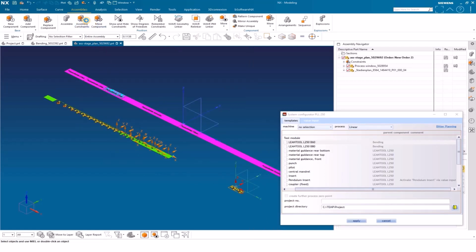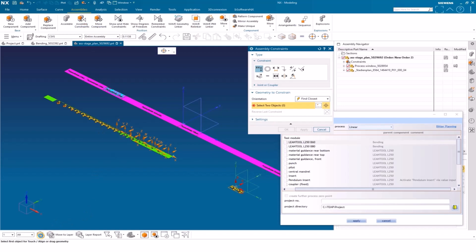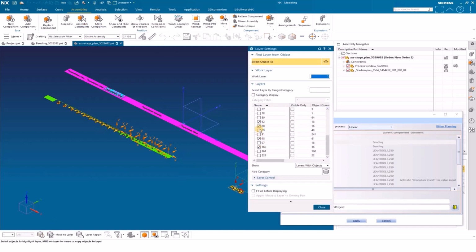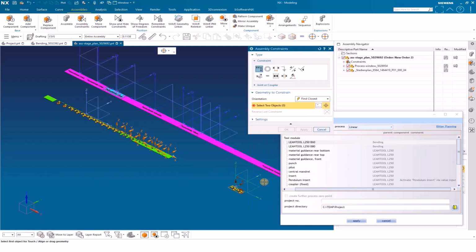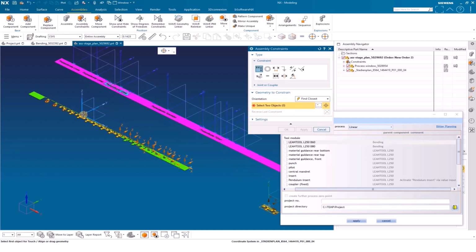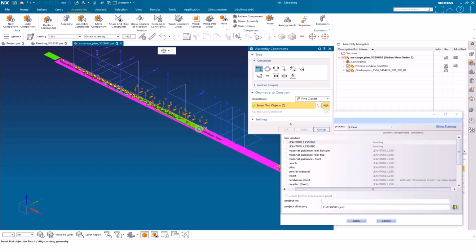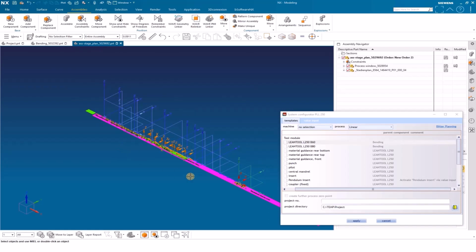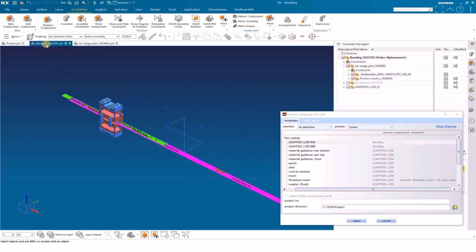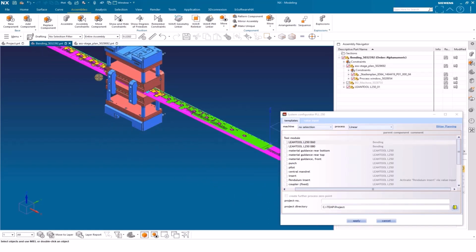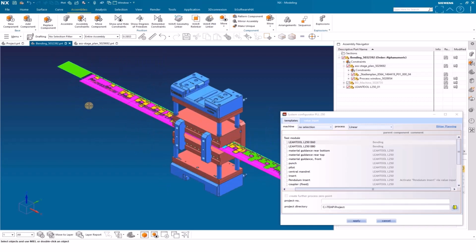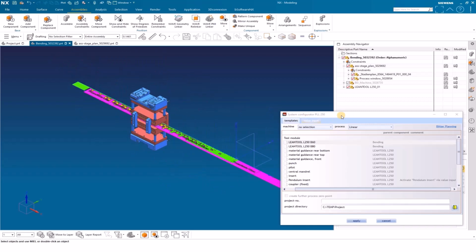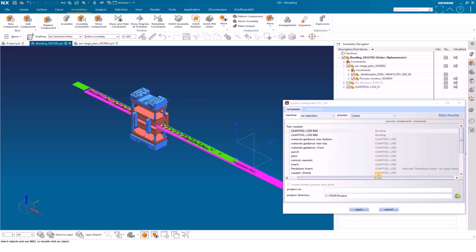Positioning is done via coordinate systems. The required coordinate systems are displayed with layer 80. The strip lies on the process window cutting and linear. After the strip has been installed, you can start with the individual components, like punches. For the individual parts, the folder has to be changed manually.